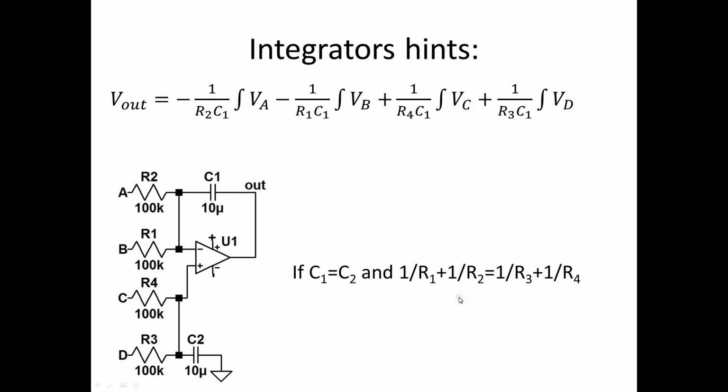Now sometimes it's not going to work out and you'll need an extra gain term. So if this side turned out to have a larger gain than this side, I could add another resistor and just tie it to ground. Same thing here. If I can't get this gain to equal the sum of these gains, or these ratios, I just add a dummy variable and set it to ground. And it works quite well. And if you walk around the building, you can see circuits where people have done that.